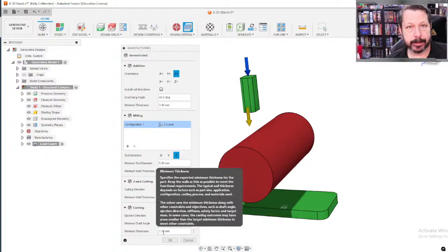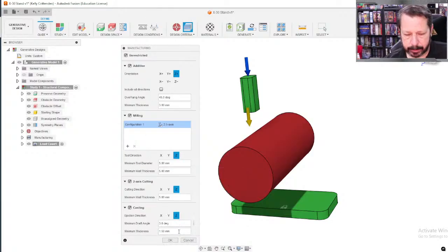That has to do with the fact that at some point it's too thin of a cavity to fill with either aluminum, if you're doing aluminum sand casting, or even if you're injecting plastic under pressure. There's still a minimum thickness: you can only get so much material into the mold before it cools if it's really thin. And sometimes it doesn't cure right if it's really thin. So we turned on all of those.